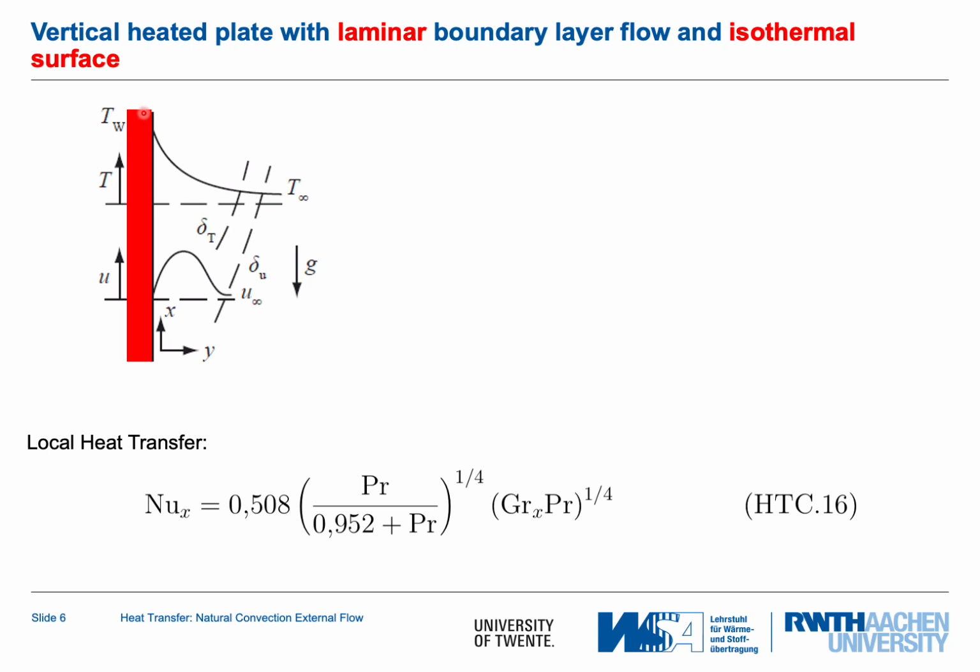Temperature of the wall at 0, going down to temperature at infinity, and there is of course a certain thermal boundary layer. The ratio of these two boundary layers depends on the Prandtl number. The x direction is the direction of the flow along the plate. The y direction is the direction normal to the plate.